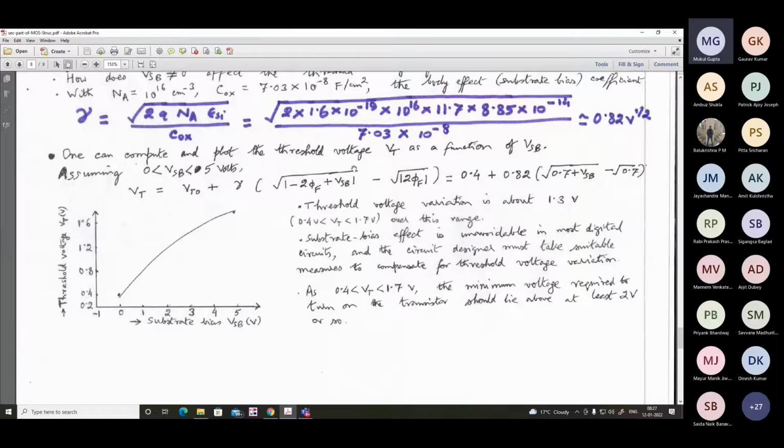In general, we are considering the n-channel transistor. So for this, source is at positive potential with respect to body. So then this will involve the total expression. The generalized expression will involve the presence of the zero bias threshold voltage and gamma, that means the substrate bias coefficient. We have to consider this sub expression, that you have to keep in mind. Now, VSB, the source substrate bias potential, can vary over the range 0 to 5 volt.